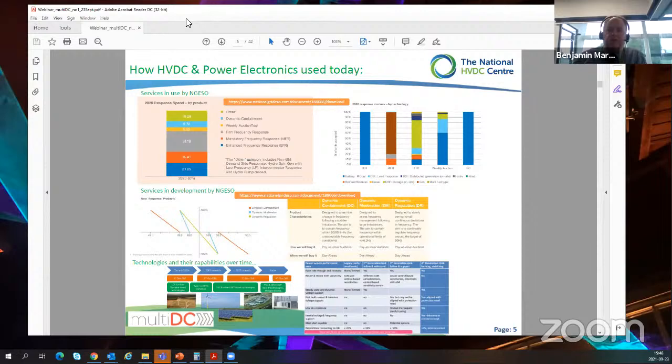And essentially this is mirroring what's happening with technologies. Increasingly we're getting technologies such as wind, such as batteries, such as interconnectors capable of very fast responses. However, these are services which would not inherently come with inertia. And in terms of the GB system, the legacy is that we've got a number of system-referencing converters, which are around 20% of the overall volume. About 80% of the converters connected to date have some degree of frequency response capability, and around 50% of the converters have the potential to be retrofitted with faster and more capable responses over time.